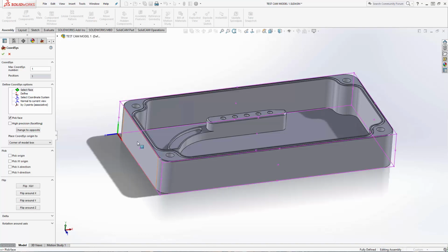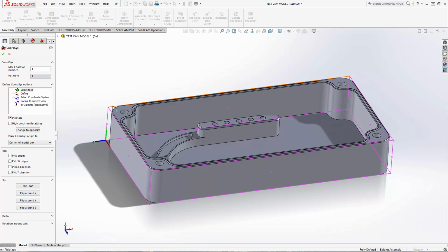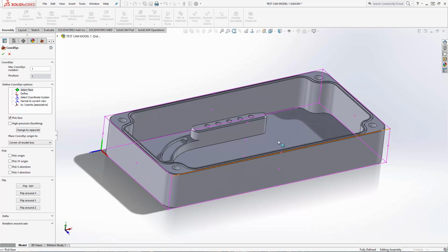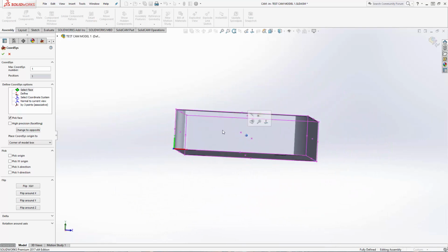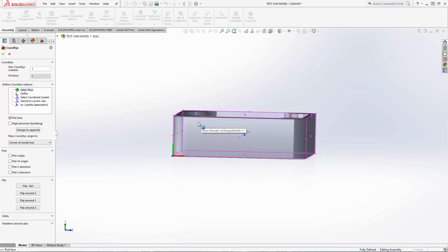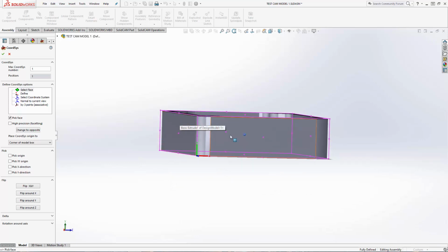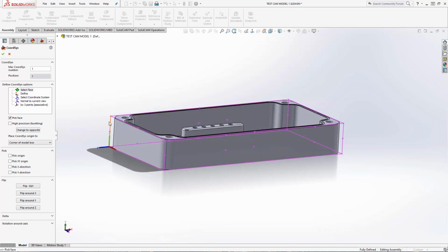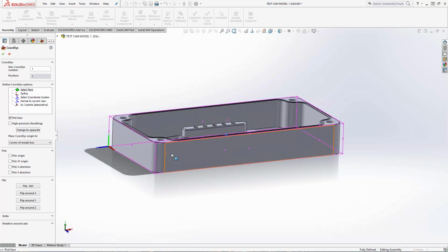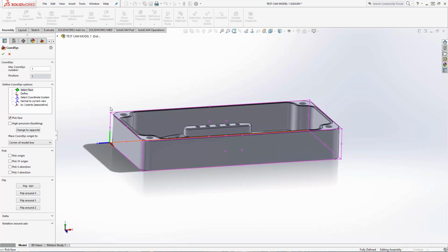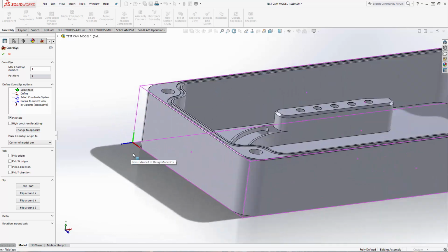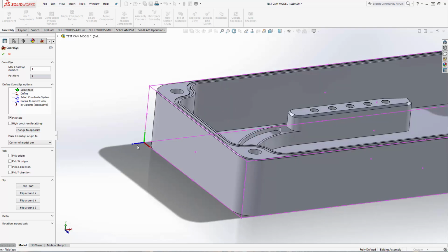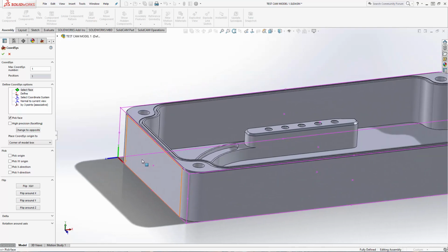And you can see that what the system's doing there is it's creating this mesh work box that you can see pictured in pink, and that is a box which encloses the part. So there's no offset between the maximum extents of the part and the box itself. It's the smallest 6-sided box that can enclose this part. So that essentially represents the limits of the part. And it's also placed a coordinate system in one corner of that box. By default it's picked this corner down here at the left.